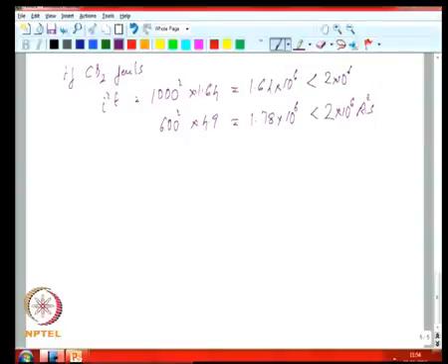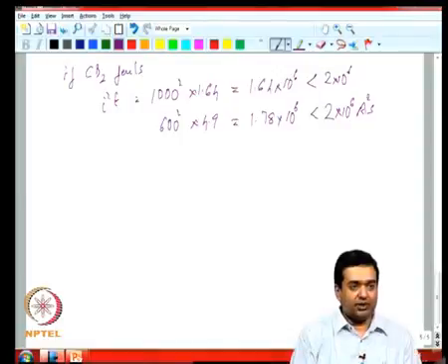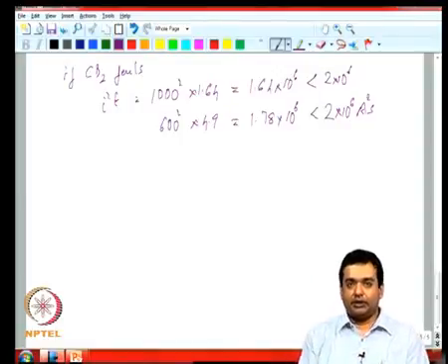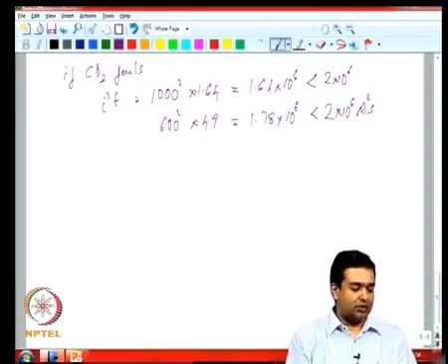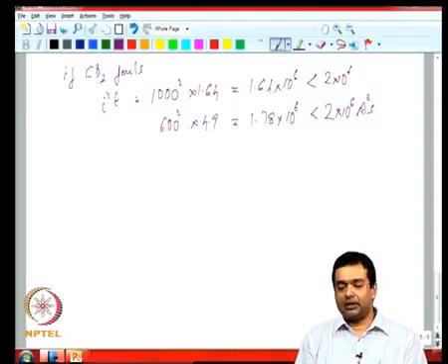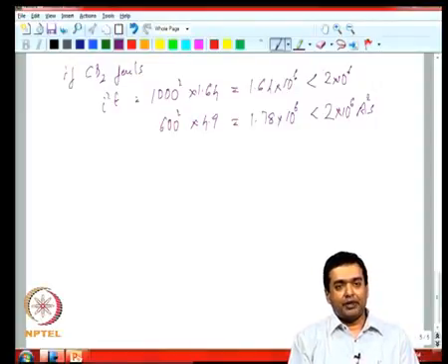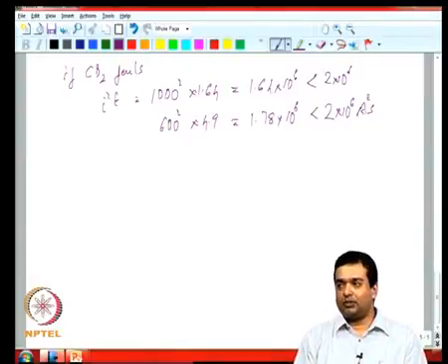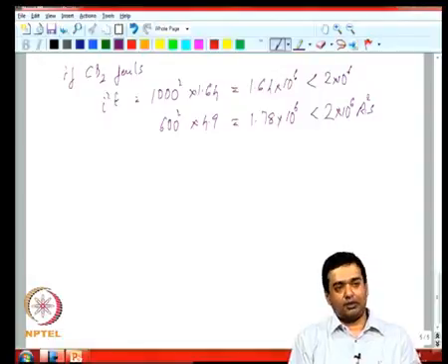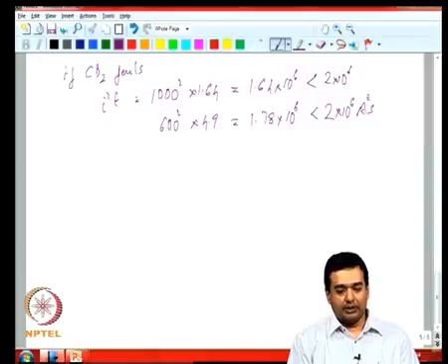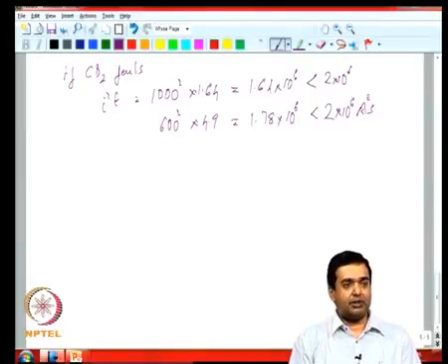So, the next thing that we have in this situation is that we had identified 3 zones: zone 1, zone 2 and zone 3. What happens for a fault in zone 3? Ideally, we have not indicated what protective device is used in zone 3. It could be a circuit breaker or it could be a fuse. The question is, will the breaker CB2 act as a backup, and if it is acting as a backup, what is the fault I square t that is happening in zone 2?